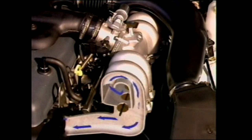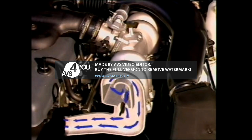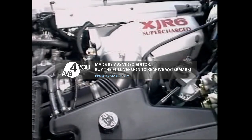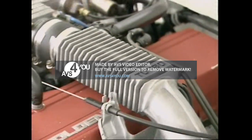Variable inertia manifolds can vary the effective manifold length in 2 or 3 stages to extend the torque curve over a wider RPM range. Generally, long intake pipes improve cylinder filling and therefore engine torque at lower engine RPM. Shorter pipes improve cylinder filling at higher RPM. Cylinder filling can also be improved by using engine-driven supercharging and by turbocharging.